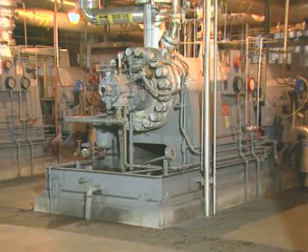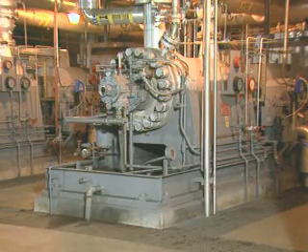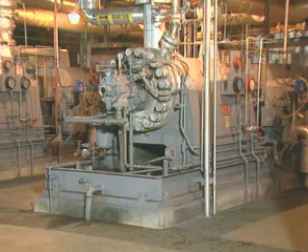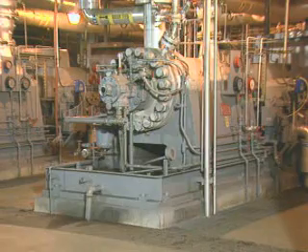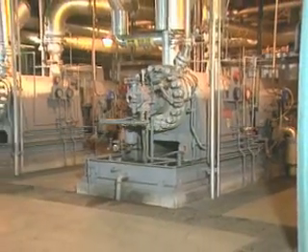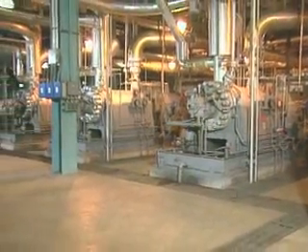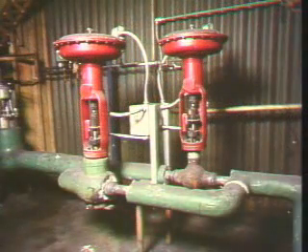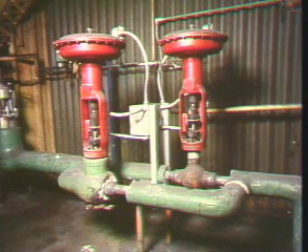If a pump has a minimum flow requirement, a flow rate less than the minimum causes higher turbulence and greater friction, which generates heat in the pump. So recirculation lines and valves are used to maintain minimum flow and prevent overheating. If flow through the pump goes below the minimum flow requirement, the valves in the recirculation line are opened to maintain minimum flow. But when flow through the pump is above the minimum level, the valves in the recirculation line should be closed.